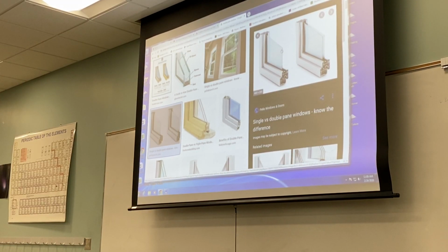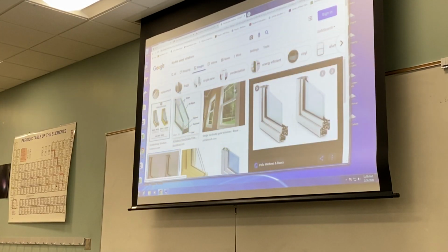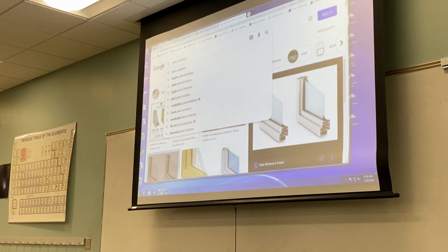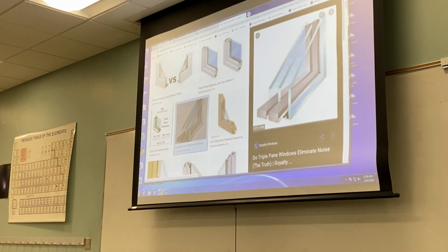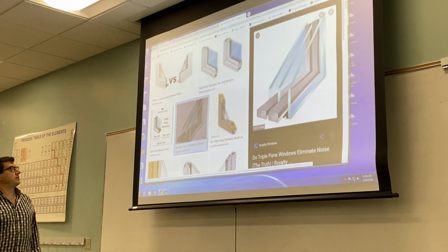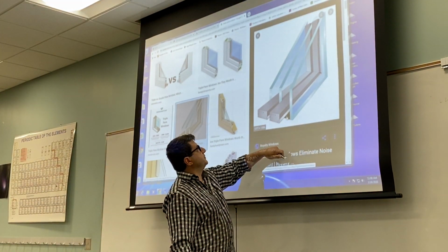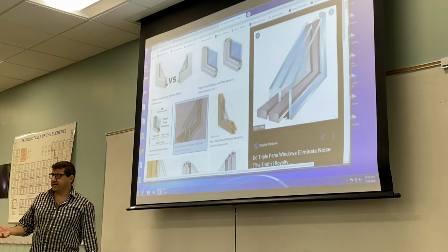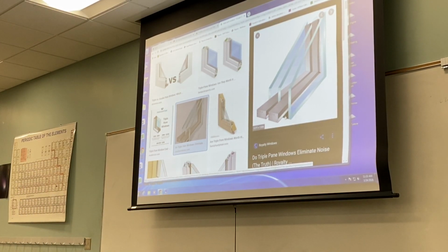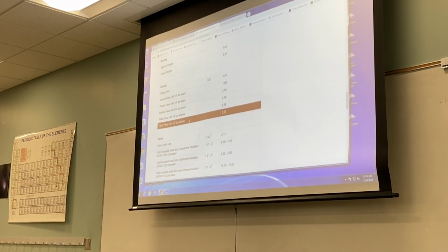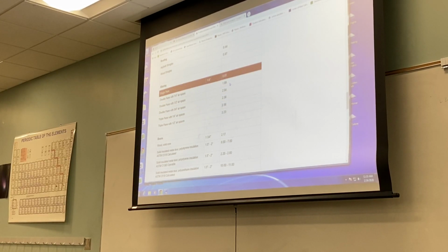This is a single pane. See here, the double pane, with the air layer. Like that. Pretty good. Let's see what the triple pane looks like. It's pretty good. Wow. And then you're adding air. Air is a heat conductor, but its insulation is better than the glass. So you are definitely saving money. The R value in the triple pane was 3, compared to the single pane 0.91.